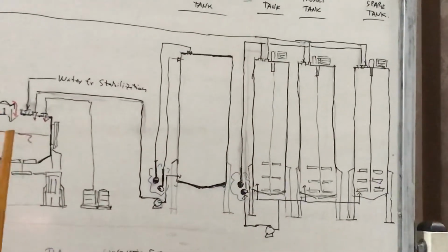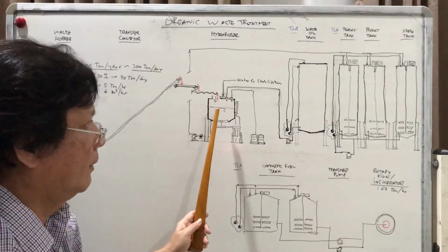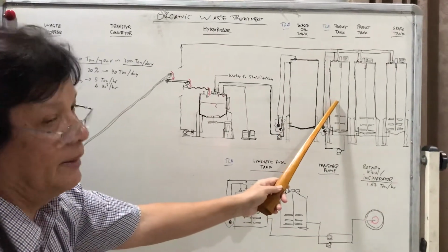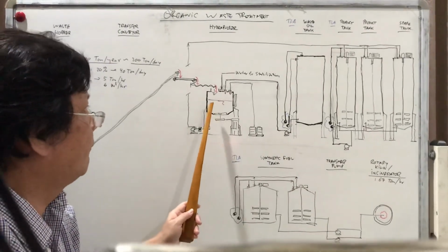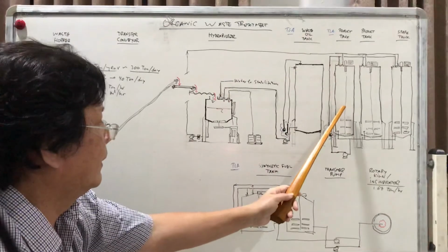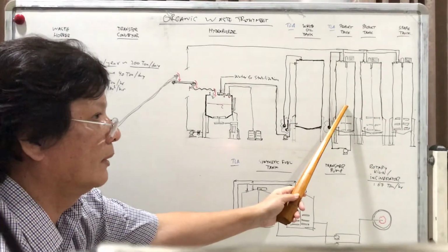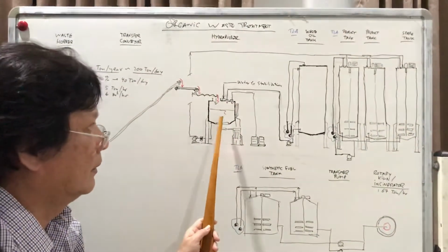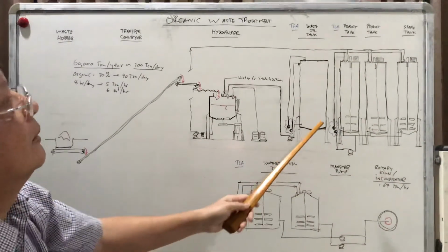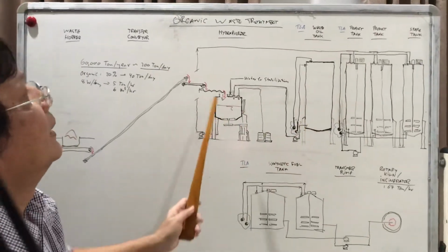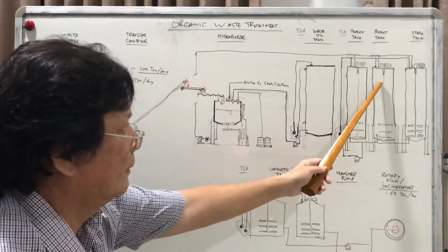You need to make several batches of process, because this tank is about 80 cubic meters and the hydropulper is 2 cubic meters. So you need to collect 40 batches to fill this tank. After this is full, you start again with the next batch into the next tank.